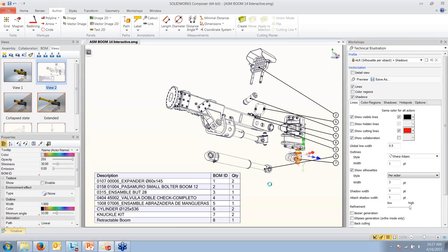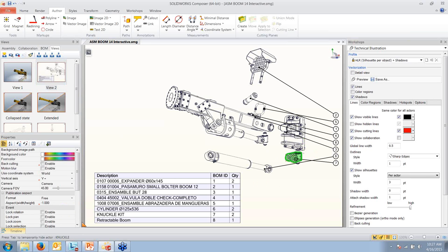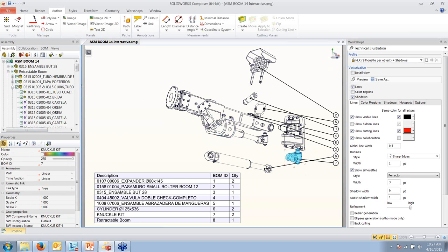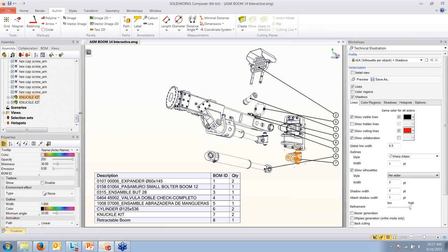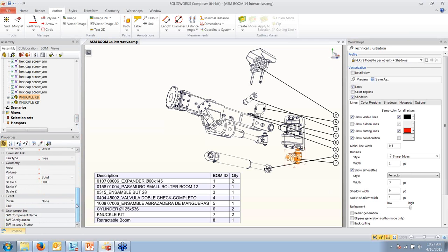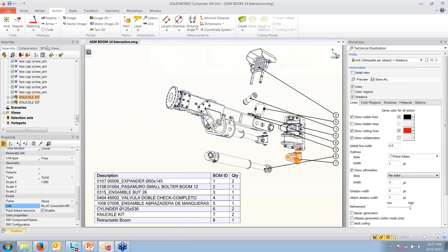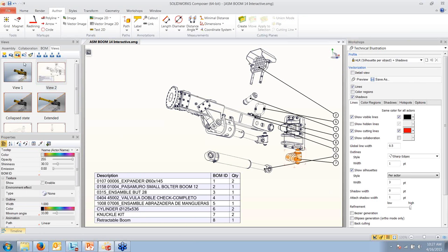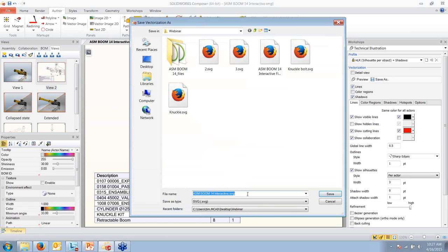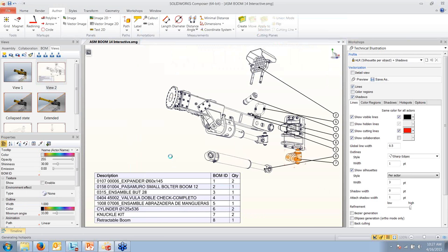Back to our big exploded bill of materials. And I'm going to grab that whole part. It's generally good to grab them as a part selected, so they're in orange, not as a full assembly select. Your selection tool is very specific that way, so you have to keep a little bit of an eye on that. So we'll link this to number 2, and we want that to be the file. So when I click that, it will open up file number 2. We will again save our view, save as on this entire technical illustration file.